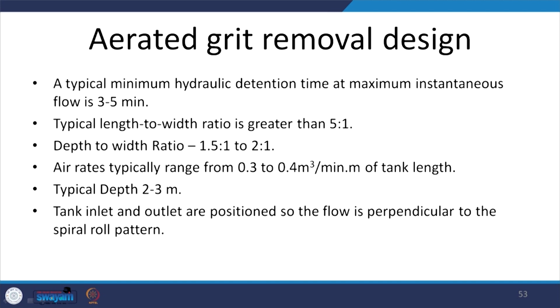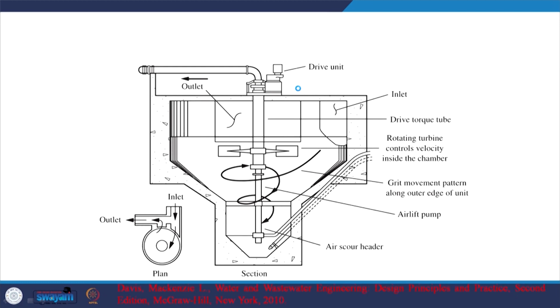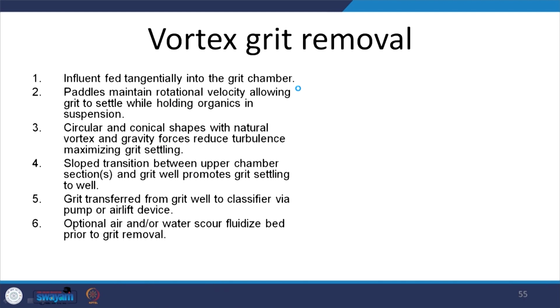So, here what is the HRT that we are trying to maintain? It is 3 to 5 minutes, and the relevant dimensions or design parameters are given. Being a UG course, we are not going to go into that, but retention time, as you see, is not high. Hydraulic retention time, as in how much time my water is spending in the relevant system, is not high, 3 to 5 minutes.